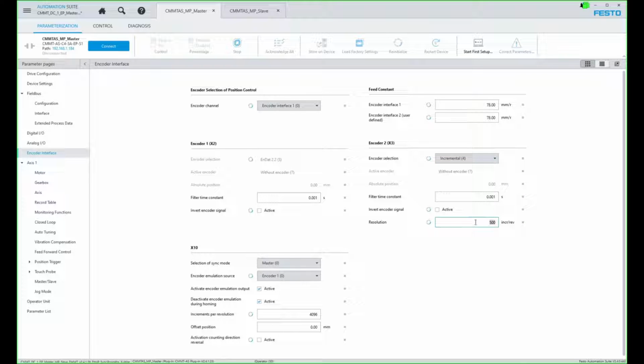We're going to type in 16382. 16384 is the max. If you do that in some versions of this software, you can corrupt the controller altogether. 16383 is an oddball number. It's an odd number. I don't like odd because it doesn't do calculations well, so I'm going to use 16382 in all circumstances. I'll get to why that's configured like that in a second.